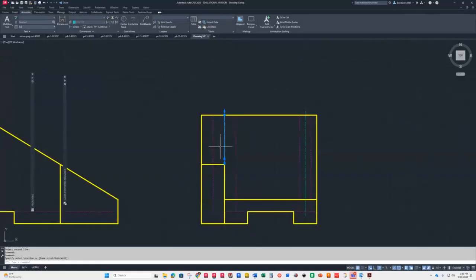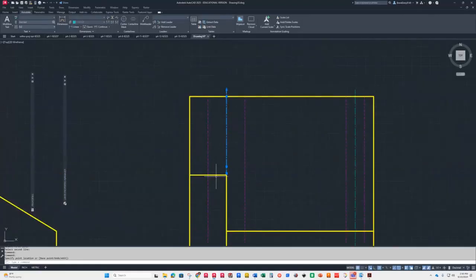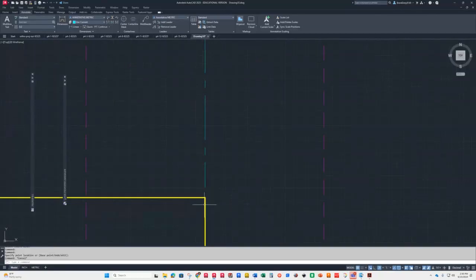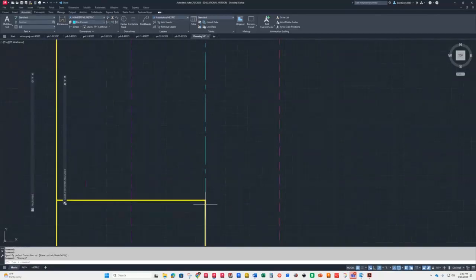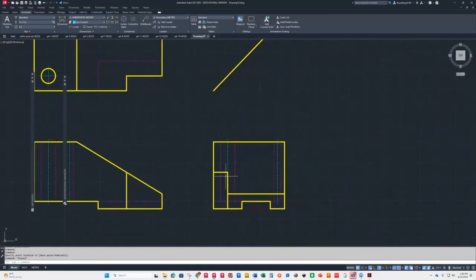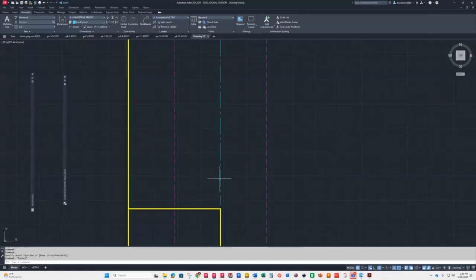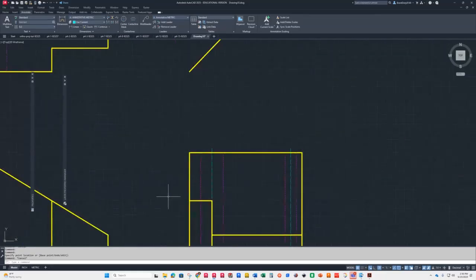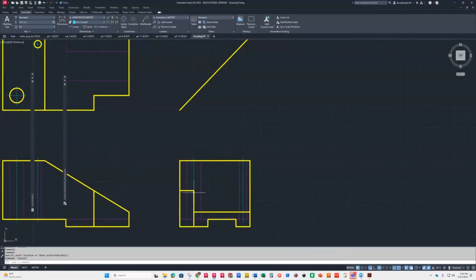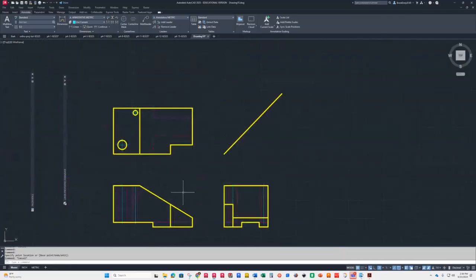And what this does is it still gives us the center line like we want, but it's not crossing over the dot or the solid line, okay? Now, how far of a gap, I don't care. Just make sure there's a gap. And that's what it's supposed to look like.